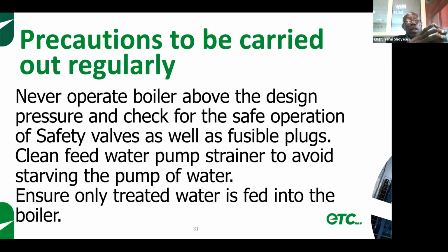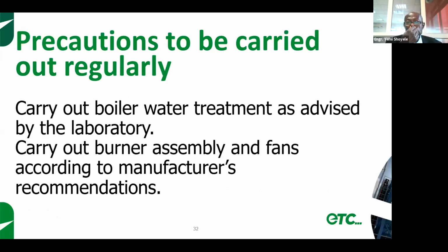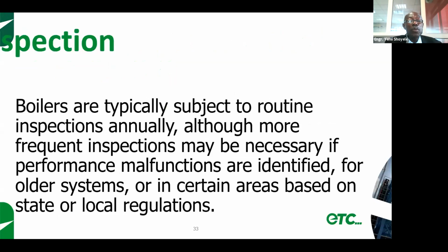Clean the water pump strainer to avoid starving the pump of water, and ensure that only treated water is fed into the boiler. Carry out water treatment as advised by the laboratory. This is very important, so you don't have problems down the line. And now carry out maintenance of the burner assembly and fans according to the manufacturer's recommendation.